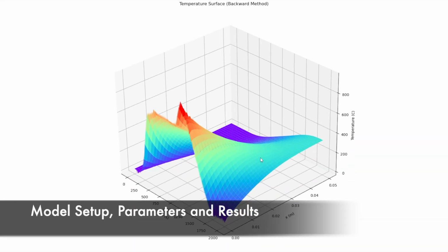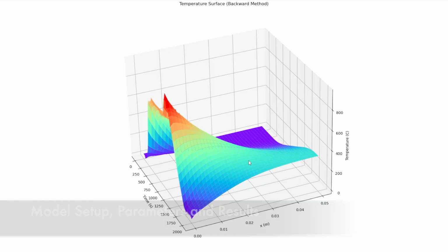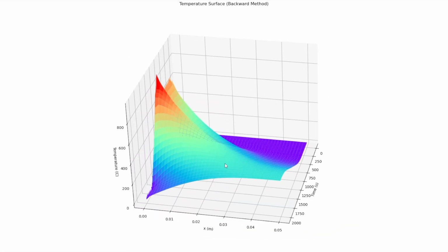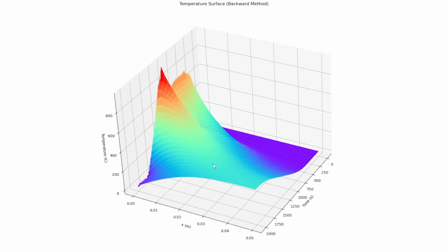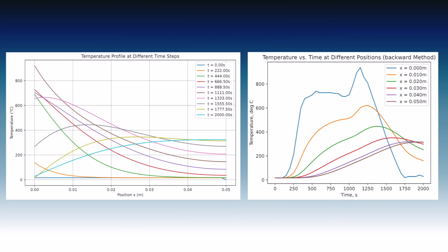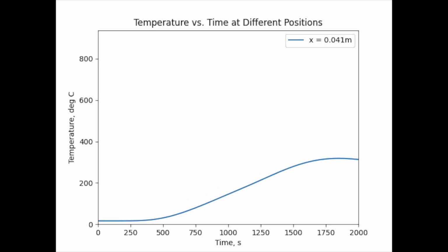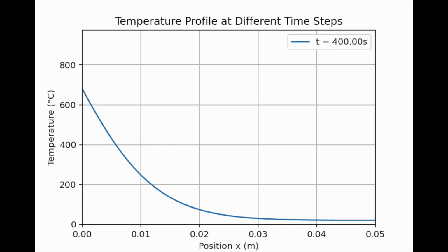This three-dimensional graph shows temperature distribution for all spatial and time points. The temperature is generally the highest at the outer surface, where the heat is applied. The inner surface temperature gradually increases over time. Two graphs, temperature versus time and temperature versus distance, are generated as perpendicular slices of the 3D plot. Multiple slices are compiled together as shown in the GUI, and a GIF is created to compare more slices without clutter.